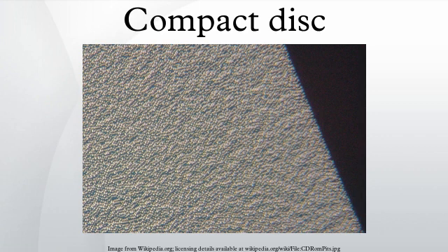Once opened, the disc substrate is removed from the mold by a robotic arm, and a 15-millimeter diameter center hole is created. The time it takes to stamp one CD is usually 2 to 3 seconds. This method produces the clear plastic blank part of the disc. After a metallic reflecting layer is applied to the clear blank substrate, the disc goes under a UV light for curing and it is ready to go to press.